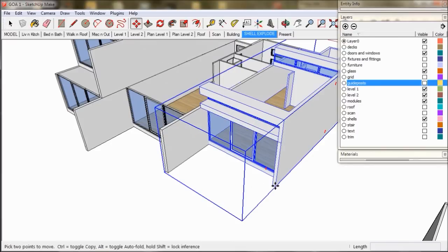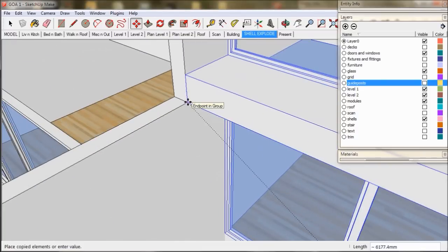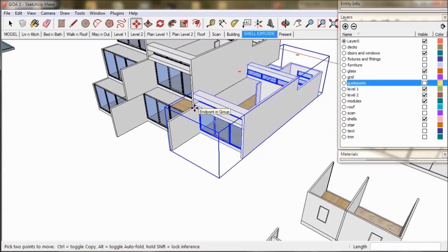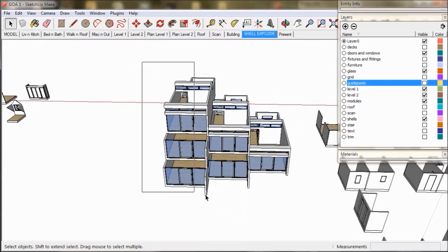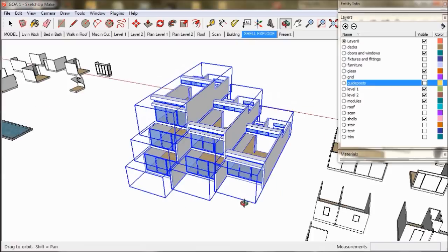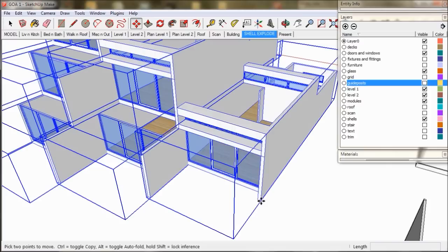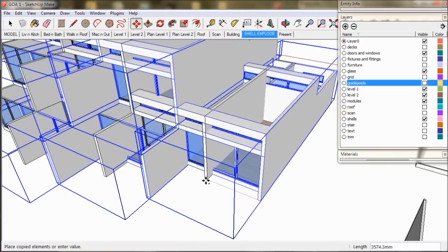And now for the outer apartment. We'll grab it by the bottom and move it over in the same pattern, and we type ×2 to make another copy. Now we select all, copy, and move it in the red direction 9 grid squares, which is 16.2 metres or 54 feet.